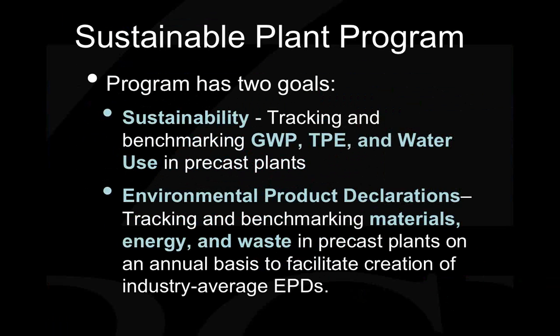They are starting to become implemented into the sustainable rating systems such as LEED, and Green Globes, which is under revision, will award points for products that have these. They are becoming an alternative path, prescriptive path within both the IGCC and ASHRAE 189.1. So by using products on your project that have these EPDs, you can meet prescriptive requirements in both of those codes. And also some owners, we've heard, are requesting them even to bid on projects. So some of the more forward-thinking owners out there, think Apple or Google, they're asking for these in order to bid on a project. So increasingly being used or requested in the marketplace.